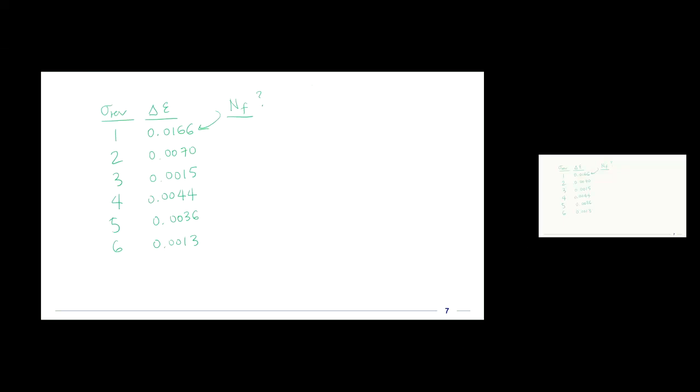The equation that I introduced in the last class said that the strain amplitude, delta epsilon divided by 2, is equal to sigma prime F divided by the modulus E, times 2 times the cycles to failure to the B power. This represents the elastic portion of whatever strain magnitudes we're applying. And then we add on to that the plastic strain.